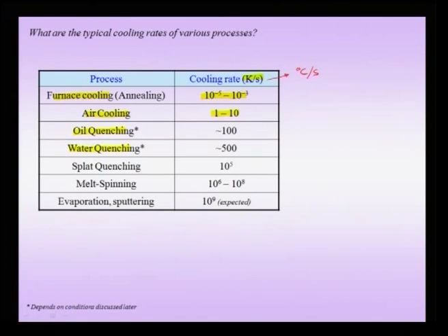And now of course, we have to note, and we will pay more attention to it in the coming slides, that the cooling rate we are talking about is the surface cooling rate, because the quenching medium is not in direct touch with the interior of the material, and therefore the medium has access only to the surface. Suppose I had a sample, for instance a cylindrical sample, what I am talking about is the cooling rate on the surface. So, this is my surface cooling rate, and not at the bulk or the interior, where the cooling rate could be different, which is controlled by the conductivity.